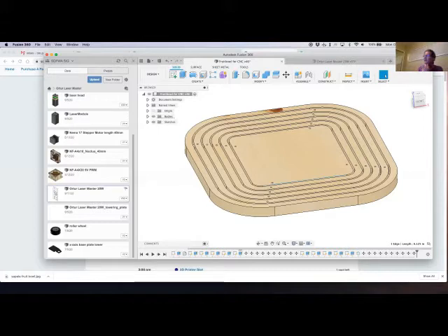Yeah. Well, that's the thing about using the V-bit, is that you clamp it until they're tight, and so in a lot of areas you don't get much gap. I'm going to have to look with the magnifying glass here to see how much gap I have. There's a couple places I have between 5 and 10 thousandths. But you don't really see it unless you're looking close.